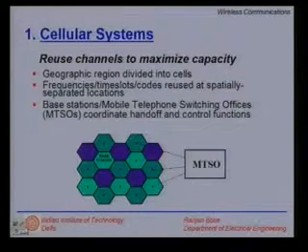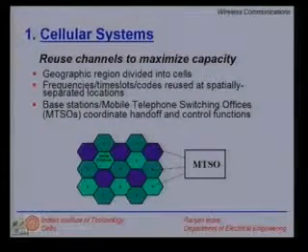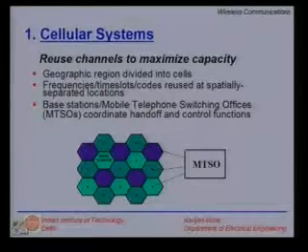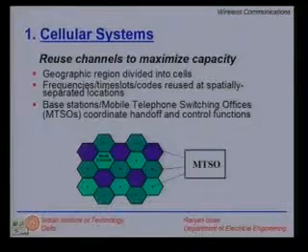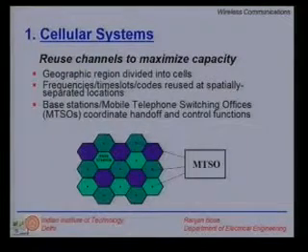Sometimes we would have a lot of co-channel interference because our user is at the boundary of the cell, and sometimes the co-channel interference can be less. So co-channel interference itself will also determine at the design stage what is the size of the cell. In real life, cells must be overlapping as opposed to what is shown here in the diagram. Here no cell is overlapping. There is a clear-cut boundary.